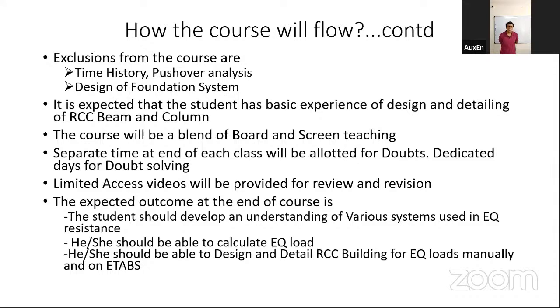As postgraduate students, you must have been studying lots and lots of analysis related to earthquake effect. I think you must have worked on time history. You must have worked on pushover. But let me tell you one thing: in practical projects, the design engineers do not understand much about time history and pushover. They are mostly happy with doing your equivalent static method and in some cases response spectrum method. But as a design engineer, the design engineer is more interested in the actual design and detailing of your RCC building.